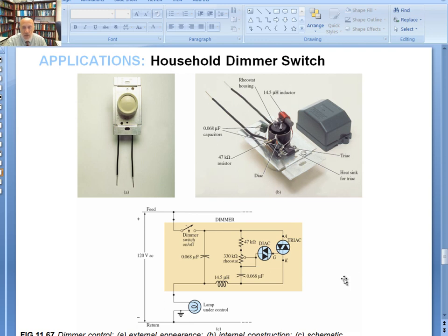So those two applications. In addition to that, they use a capacitor, which is hooked up from line to the neutral, connected in series with a lamp to avoid any spikes in the voltage, to protect the equipment that's hooked up to it. So an inductance will control the rush current to protect the equipment, and the capacitor can protect the equipment from a high voltage or spikes in the voltage.